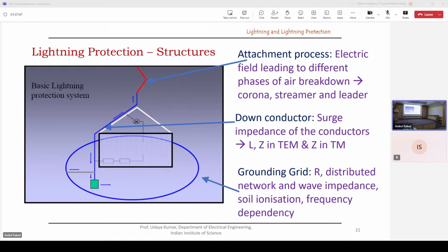Then what would happen? If it is successful, the structure will not carry the main current, it will carry induced current. And because you're providing a low impedance path, the voltage rises are controllable, hopefully. Then because the current is dissipated, people inside will not see serious potential. They'll see some potential, not serious. These are the overall concepts. Franklin thought otherwise, but we shall comment on Franklin later.